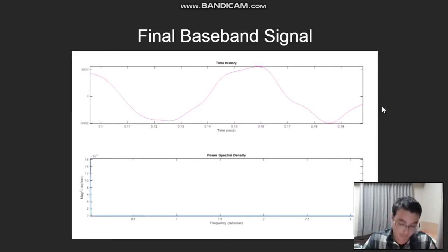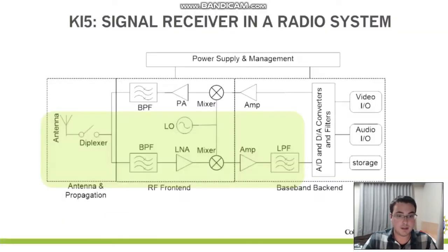So overall, what this system does is it takes information through the antenna, it isolates the information, it eliminates the carrier frequency that it was originally transported on, and then it isolates that signal even more by eliminating repetitions of that signal at higher frequencies. And then finally, with that baseband signal, you can either store it or transmit it through the radio. You could hear music. So this is how this is done.